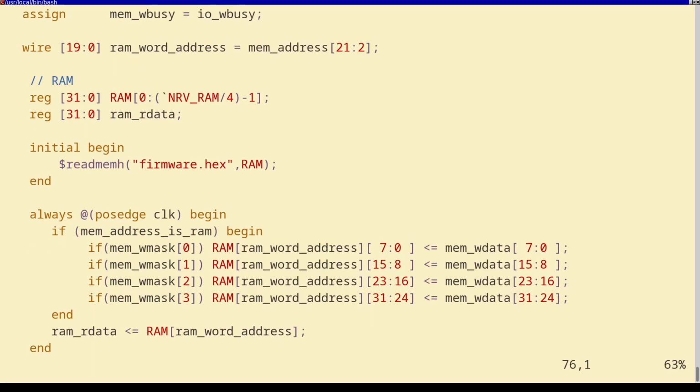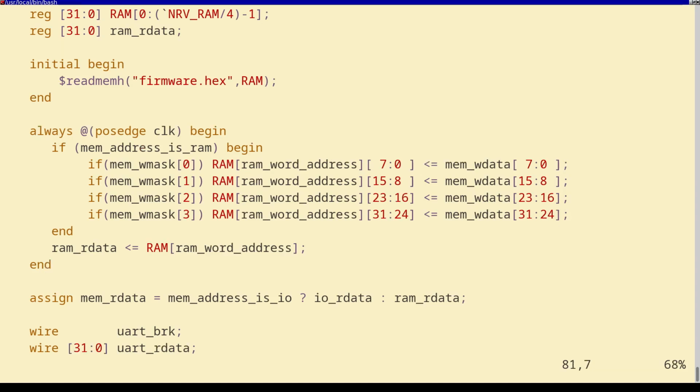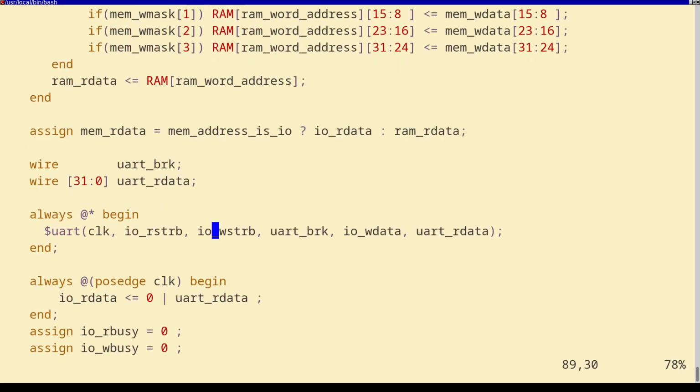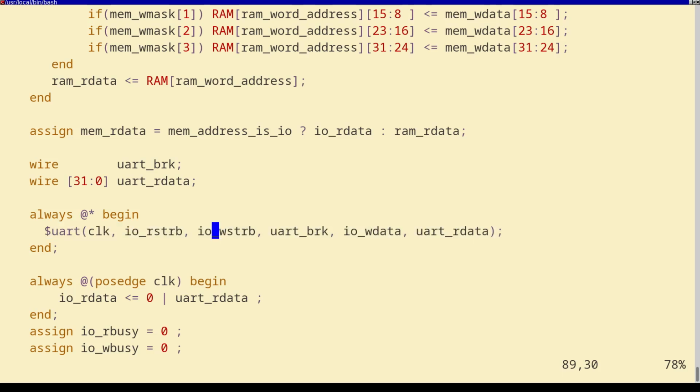We'll have a look at this. Whenever we want to write to the memory, we get the data from the RAM depending on the mask, or we write it like in this line here. All right. This is a component that cannot be synthesized, but corresponds to a UART that is going to give me the connection to the serial port that's connected to the terminal.